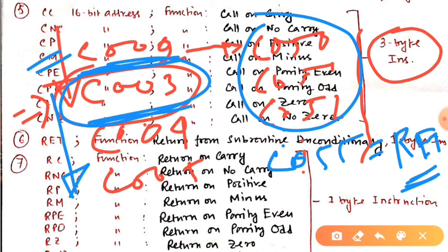Okay, so that is why when we use the return instruction, it fetches the top of the stack and it will read the corresponding memory address C003, and it will store that memory address for the time being in the WZ register pair. As we have seen, the same thing has been done in case of jump instructions and in case of execution of call instructions also.